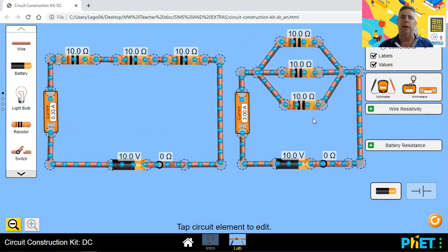Here, you calculate it with a slightly more complicated formula that you'll see on page 25. And in fact, the equivalent resistance of these 3 is actually 10 divided by 3, which is 3.33 ohms. And that's why 10 volts divided by 3.33 ohms is equal to 3 amps.